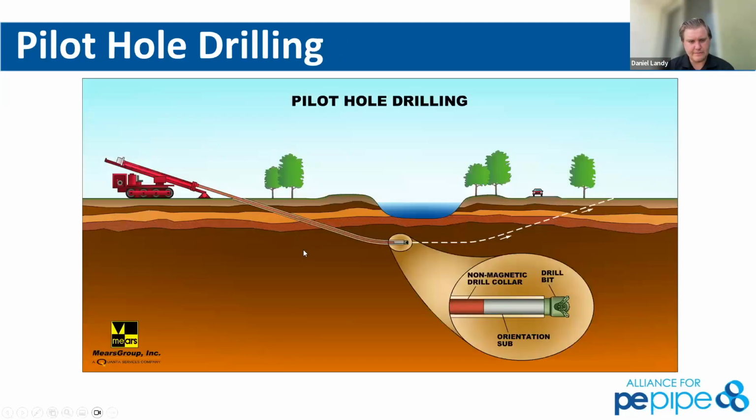Next slide, Alan. And we're going to walk you through the process really quickly. So the drilling machine itself would actually be on the left-hand side of this image, and on the right-hand side is where you'd be fusing up that pipe string. So the first thing they're going to do is bore a pilot hole. If you were going to be drilling maybe say a 24-inch pipe, you start with a 6 or 12-inch borehole.